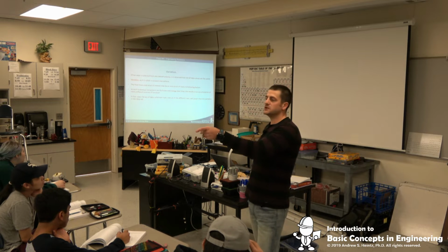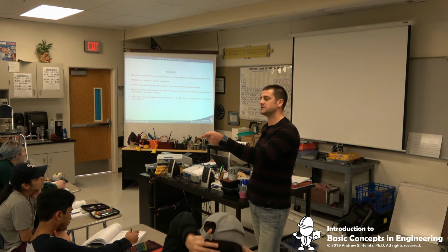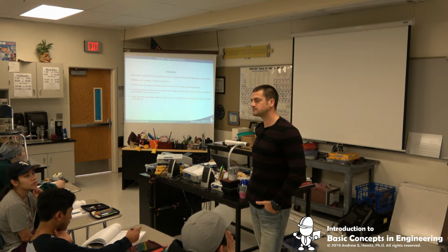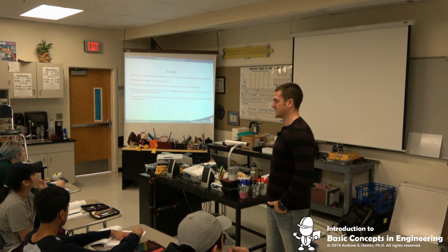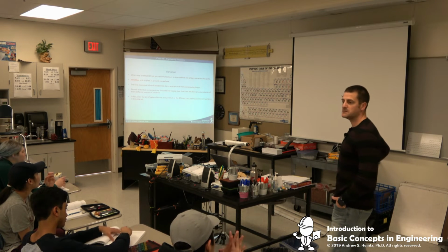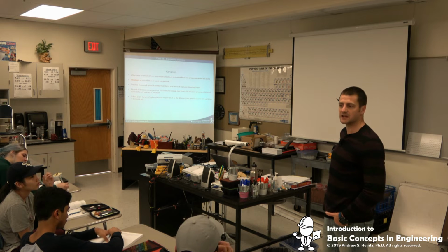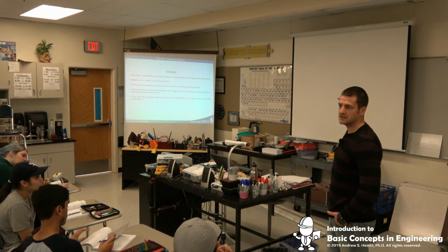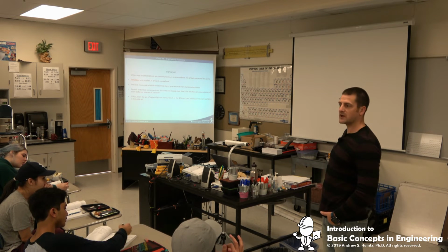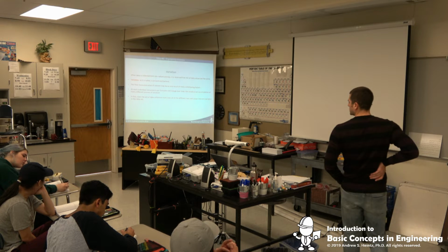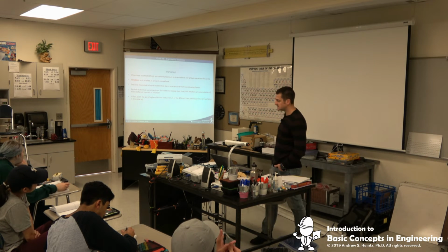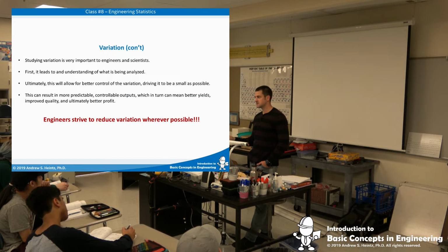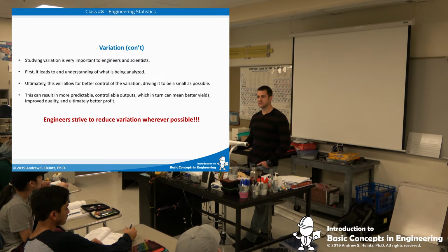And what if I asked you to go out and measure something? Would you get me the exact same measurement every single time? Why is that? Because of human error. That's exactly what I was going for. Or just variations in testing method. Error sometimes implies a negative, like you screwed up. But if I ask you to take a sample for exactly 5 seconds, you're going to be like 4.9, 5.1, 5.0. You're going to be all over the place. So the act of data collection itself is going to often introduce variation. And our job as engineers is to take that variation and reduce it wherever possible.